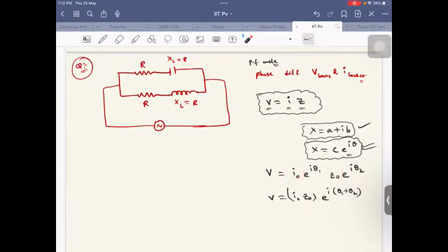Now you can clearly see the phase difference. If I ask what is the phase, or argument, of current, it is just theta 1. And what is the phase for voltage? Theta 1 plus theta 2. Then what's the phase difference, delta phi? The power factor angle, or phase difference between source voltage and source current, is the difference of these, which is nothing but theta 2.